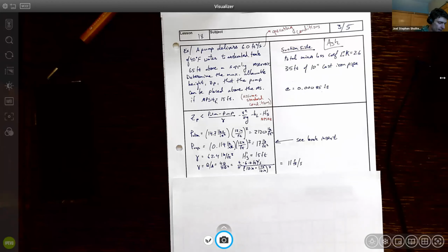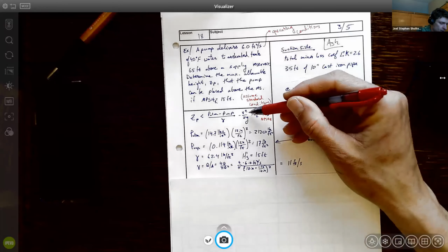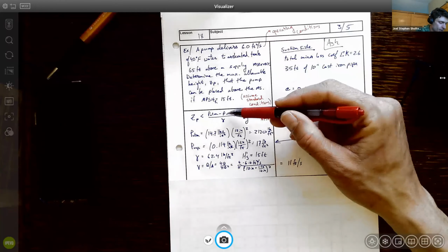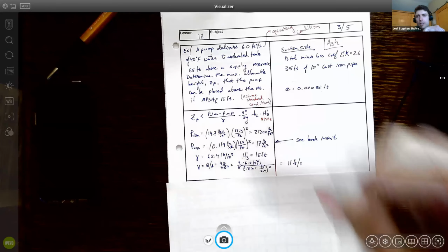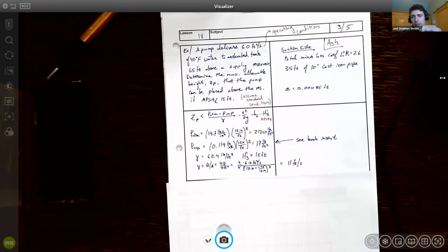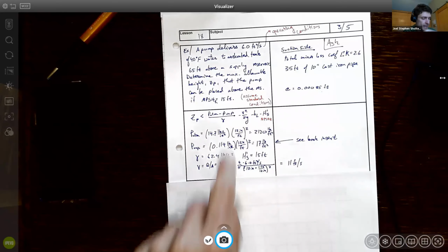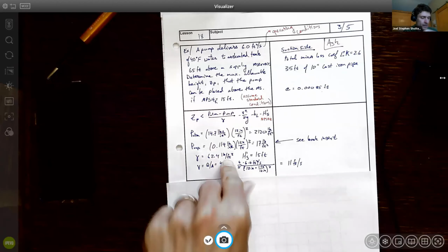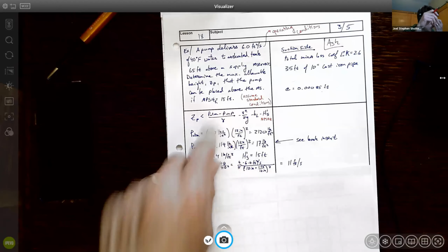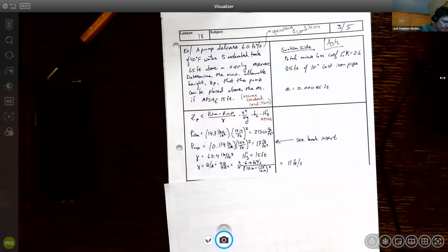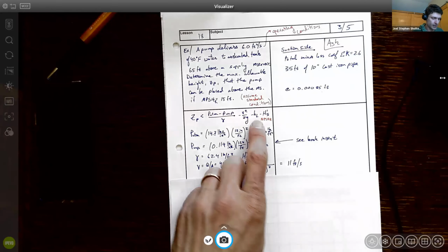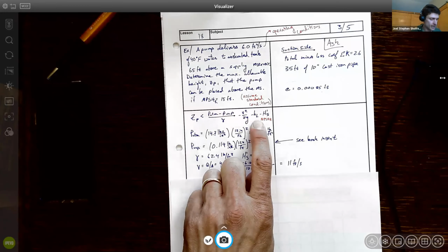Now we've got our velocity, we've got our net positive suction head that was given, we have atmospheric and vapor pressure, and we need to make sure those are in pounds per foot squared because we're dividing by gamma, which is pounds per foot cubed. So that everything comes out to feet, right? We're dealing with feet. So now that we have all those terms, we need to calculate our head loss. And that's going to take a few more steps.